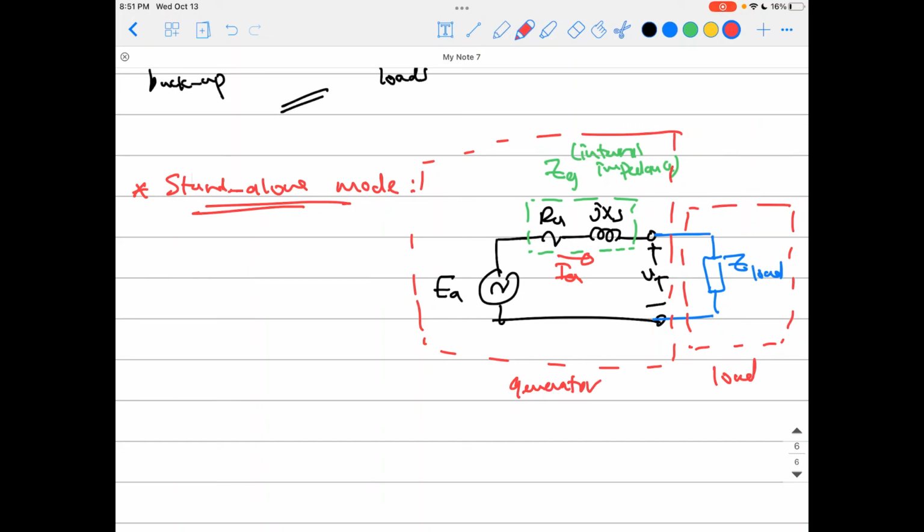So we're talking about an electric circuit solved to figure out how the current moves. That's simple because we have just a generator connected directly to the load. All the time, remind yourself that this is the per phase equivalent circuit. That means that is the impedance of one phase of the load, not the three phases. We are assuming the three phases of the load are balanced, meaning the impedances are equal between the three phases, so we can use one phase to represent them all.